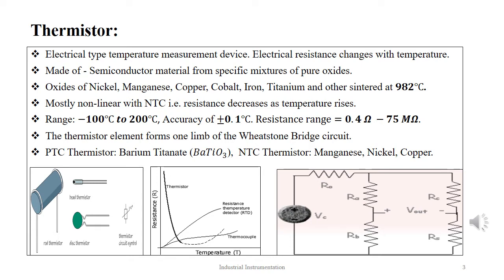Two stark differences between the thermistors and the RTDs are that while RTDs use pure metals as the sensing element, thermistors use ceramic or polymers, and secondly, RTD normally has a linear output scale for the better part of their range, while the thermistors are nonlinear temperature sensing devices.